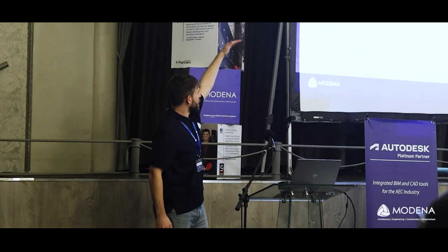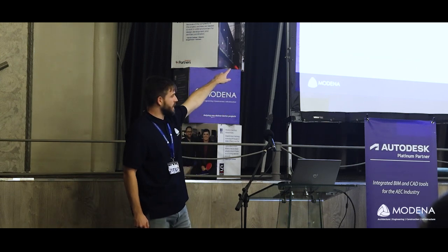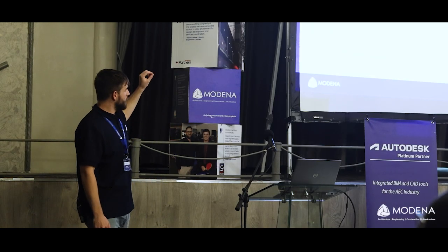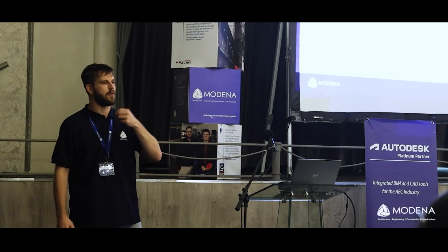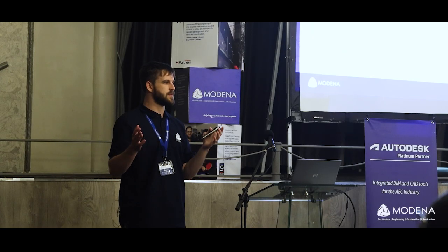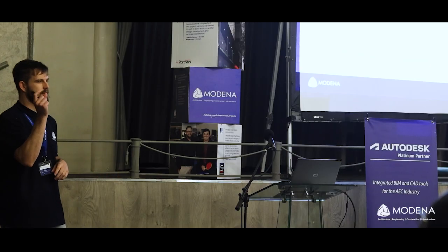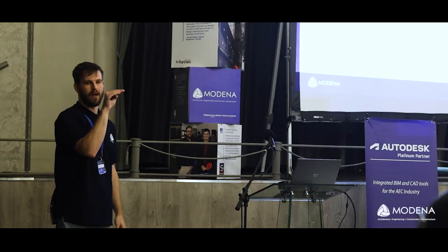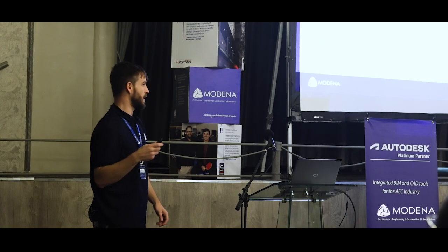So as you can see, we've got our fill value in red, cut in blue, and then we've got this orange line in the middle. And that is actually looking to make sure that as we flatline onto 0, you can decide how long you let the equation run, because there's a point of no return, or it's not feasible to get that final input value. So that will allow us to see at a certain point when you are happy with the flat line, we can then just pause that element and you can then design from there.